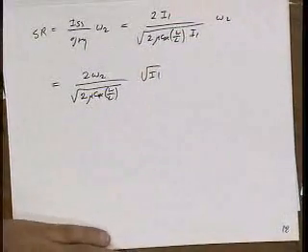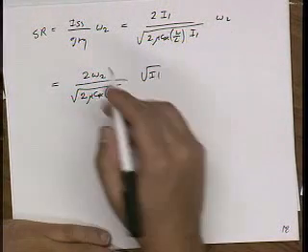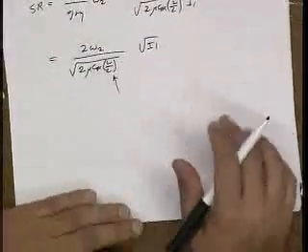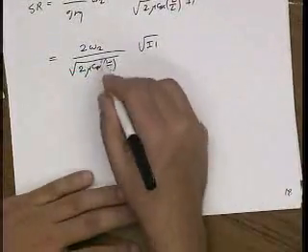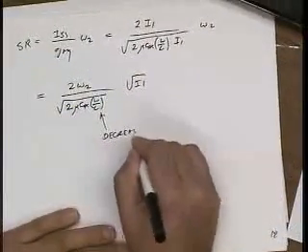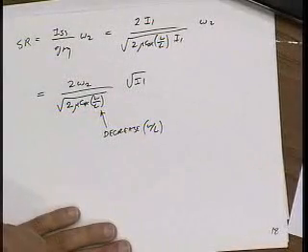So you can see that to improve the slew rate, if let's say the currents are fixed by other considerations like settling time, to increase the slew rate, you decrease W over L. Okay?